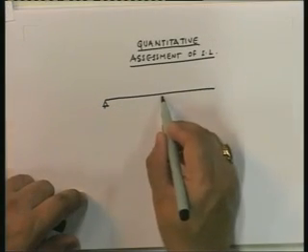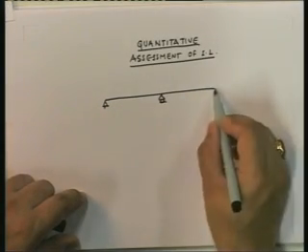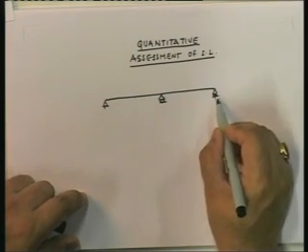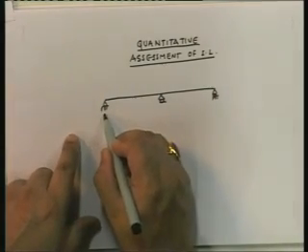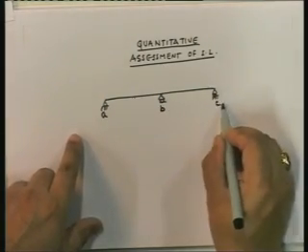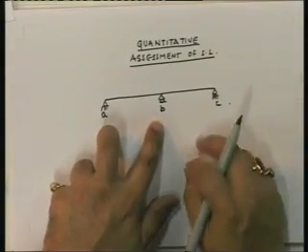For something like this, with A, B, C, note that if I knew the bending moment at B, both members AB and BC would become statically determinate.